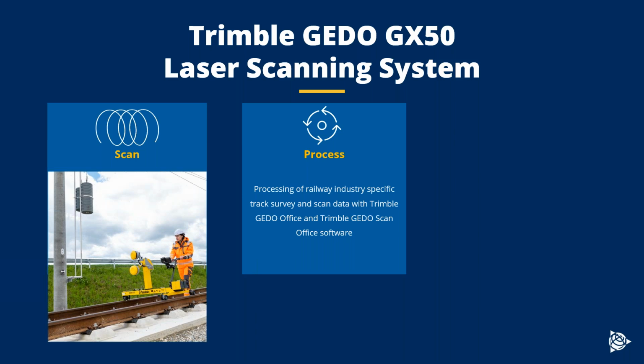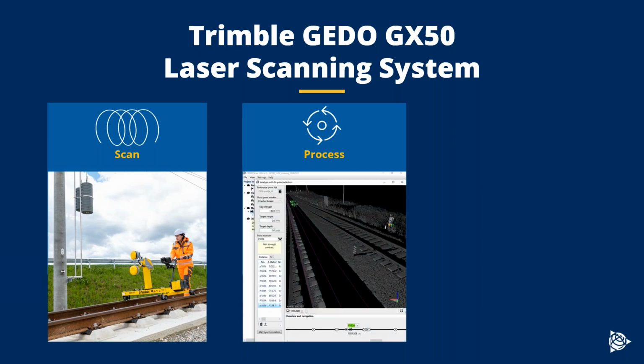It can be relative scanning, when we get the trajectory as a straight line, or it can be absolute scanning, when we get the trajectory as a 3D polyline and the whole point cloud data gets 3D coordinates.